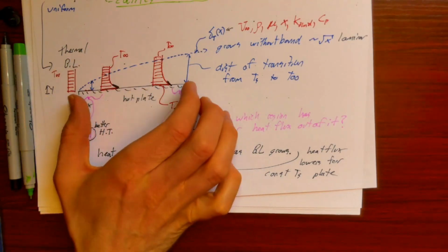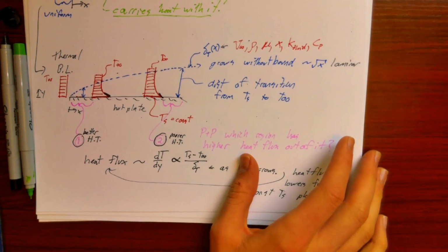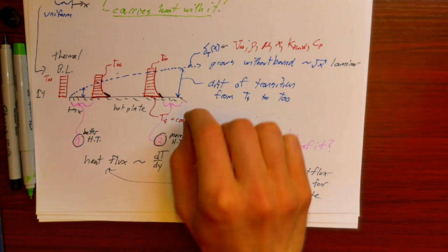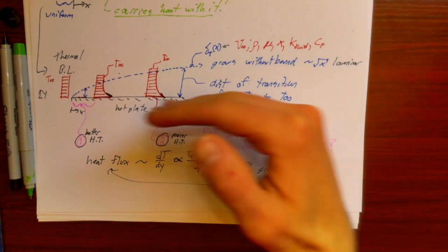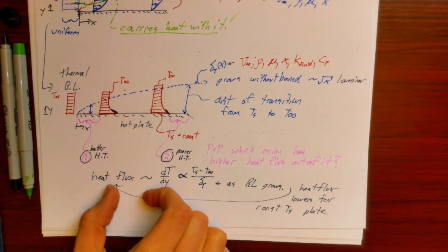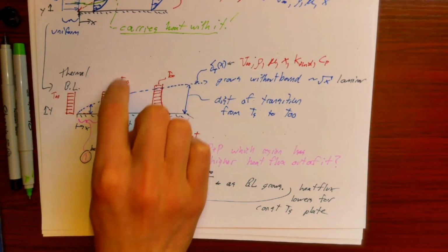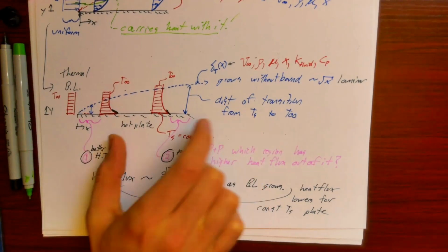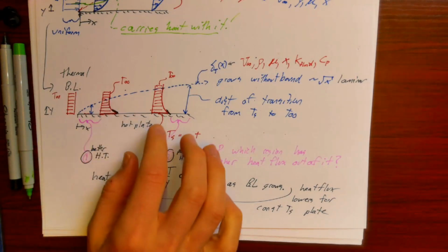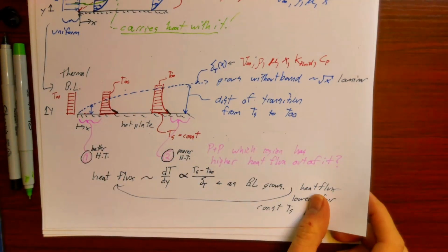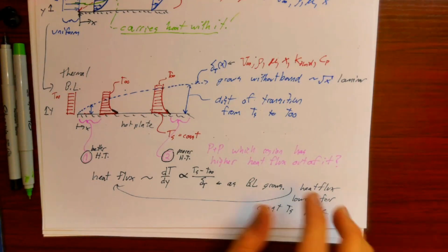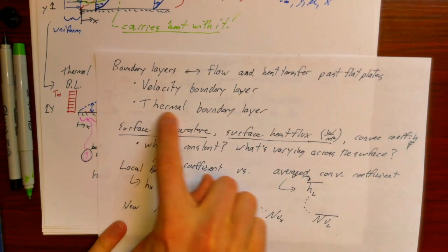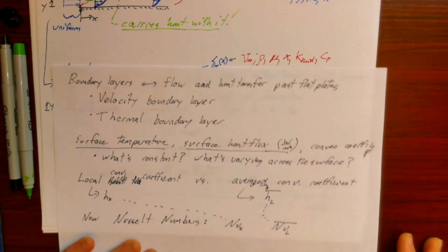When you're designing heat exchangers, like those fins for the air conditioner that you saw earlier, oftentimes rather than just have one big long fin, they'll have a series of parallel shorter plates, because then each plate will be getting the best flow. So it's better to have two short plates than one long plate in terms of heat transfer. But there might be trade-offs in other aspects of your engineering design. So this is the nature of the velocity boundary layer and the thermal boundary layer, qualitatively anyway.